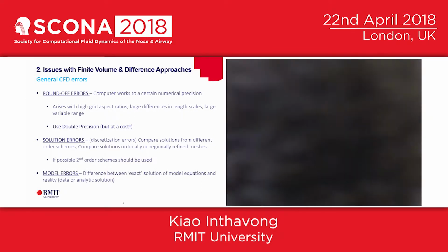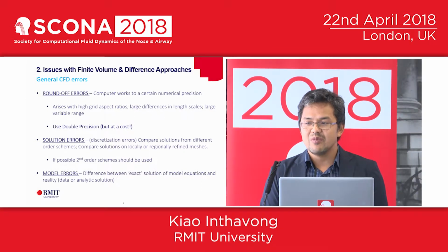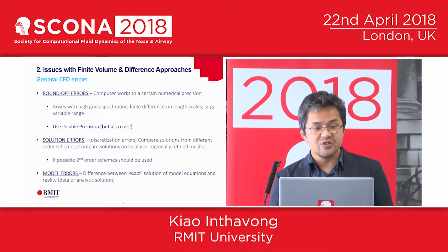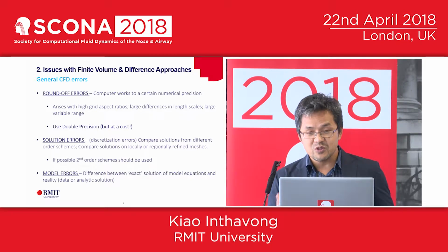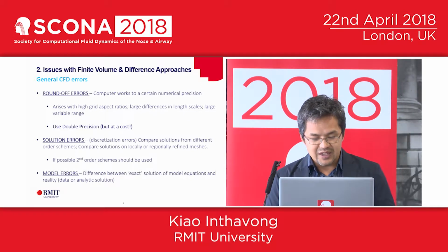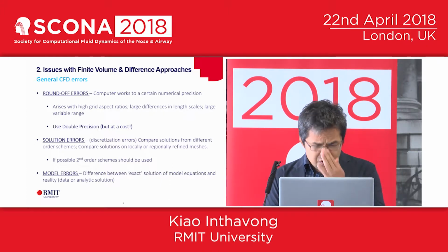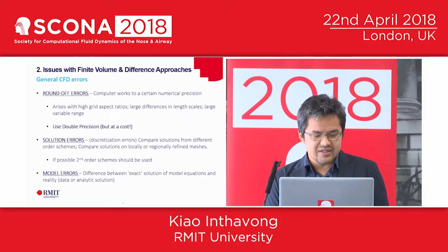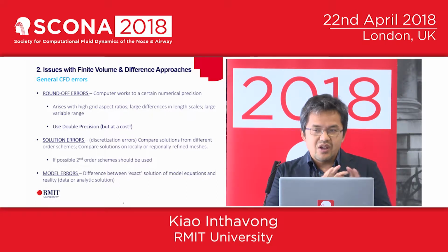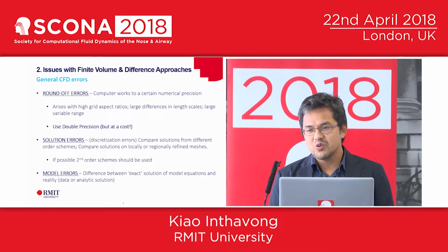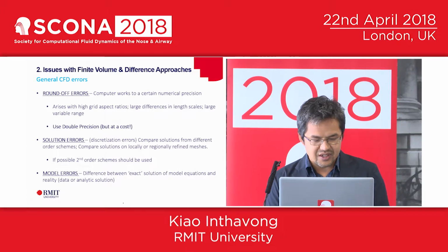So just a few issues with CFD, and my comments here are based on the finite volume and difference approaches. So depending on your software and your solvers, perhaps this may not apply to yours, but this is the experience that I've had using the finite volume approach, and in particular the Ansys package. And so round-off errors are one concern, and typically arise when you've got very high aspect ratios. And to counter that, you would want to be using double precision, but then that comes at a computational cost.